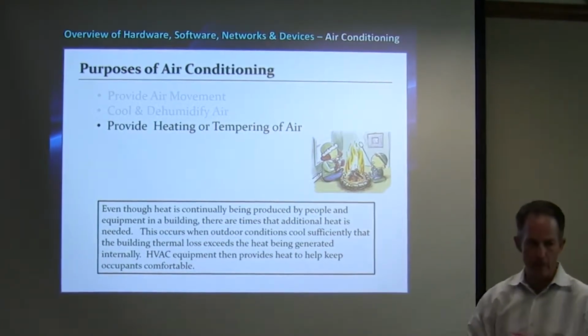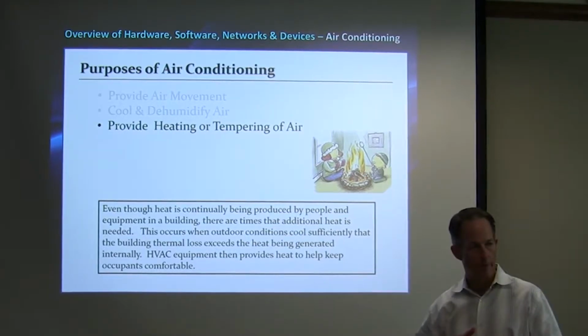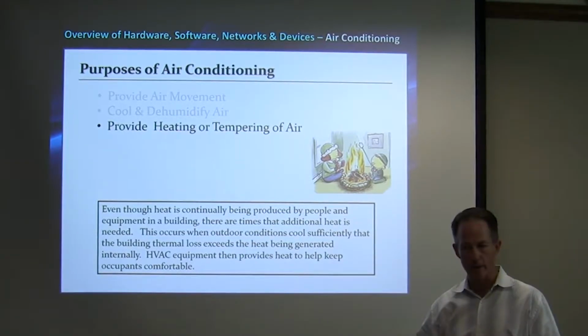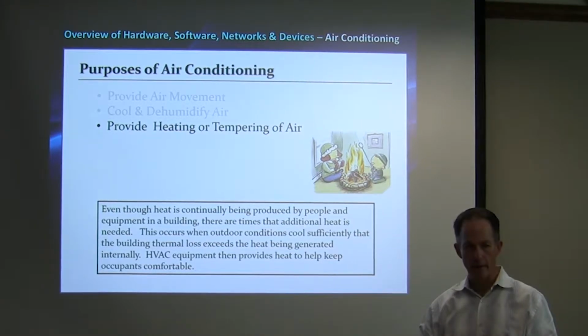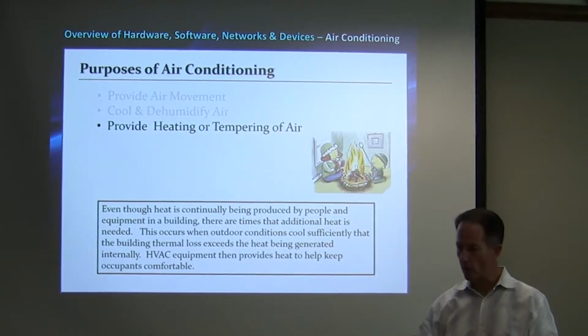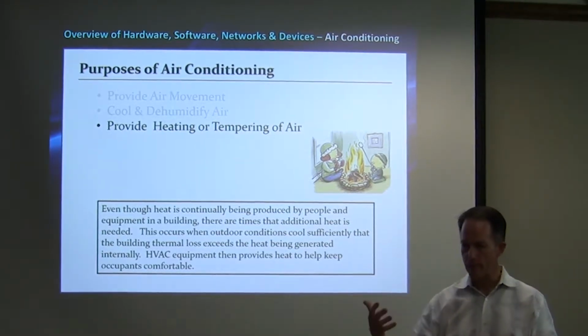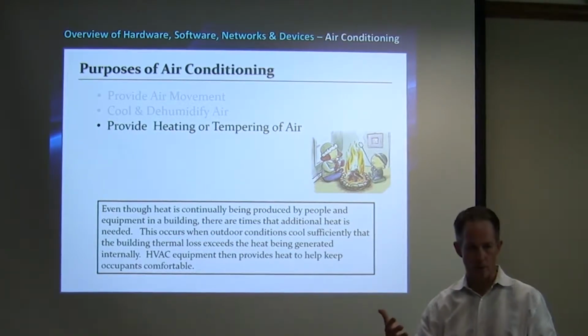Providing heat and tempering the air. So wintertime, we see this a lot where we can't bring in just straight outside air. We can use some of it, but we do have to warm some of it up. We'll mix with our return air. But if we're pulling in outside air to keep a building positive or pressurized, and we don't have enough heat, we can get too cold of air blown into the building, and then what happens to our ductwork or to the space?